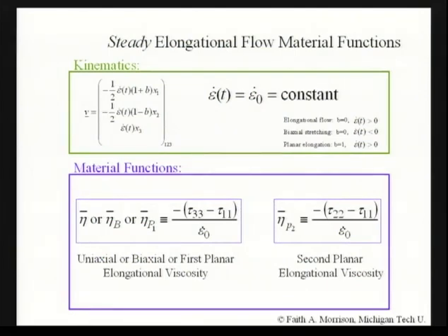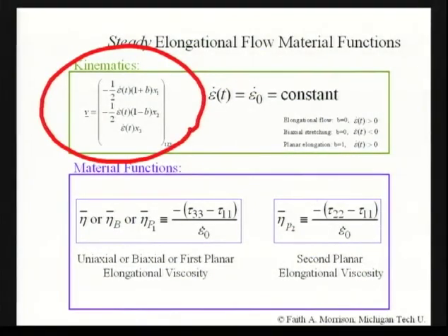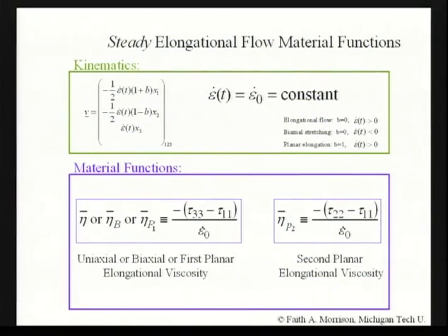Then we also talked about, finally, our elongational material functions. Again, kinematics and material function. So don't hesitate when you're asked a question to predict a material function. Start immediately by writing down the kinematics, because that has to be the starting point. The constitutive equations that you have are a function of the velocity vector. So you can always just plug the velocity vector into the constitutive equation, predict stresses. The stresses go into the definitions of the material functions. In the case of elongation, they're these eta bars.